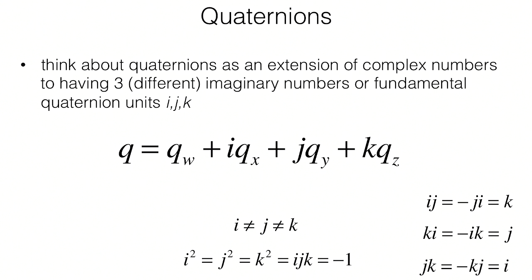The quaternions give us a nice tool set that allow us to work with axis angle representation because now we can interpolate between them, we can add them, we can multiply them. We have all these algebraic tools that are well defined for quaternions, and we're just going to use them as a container for this axis angle representation of rotations.